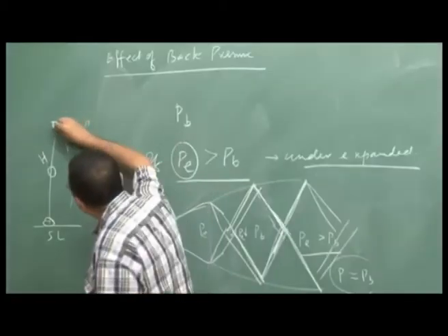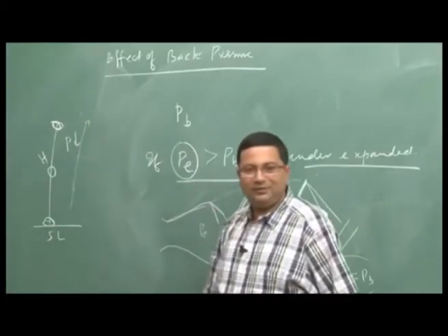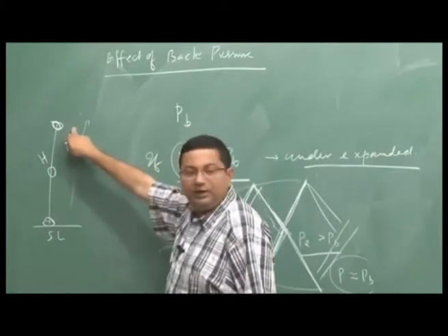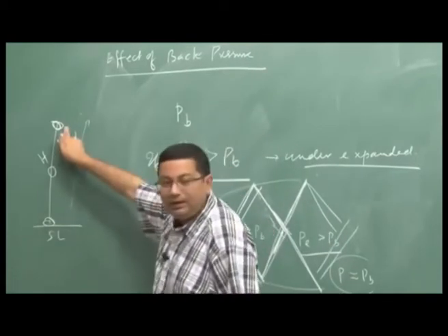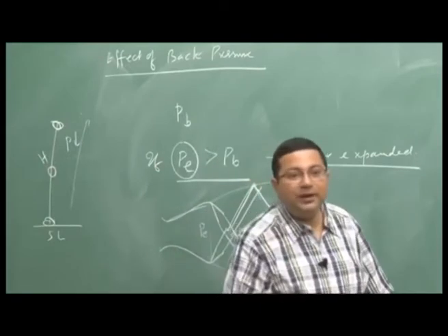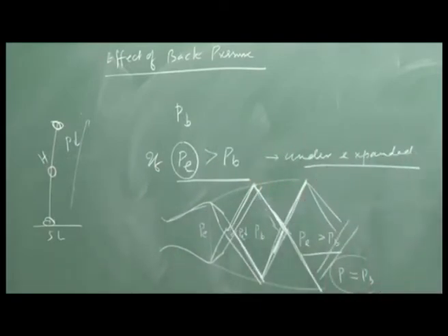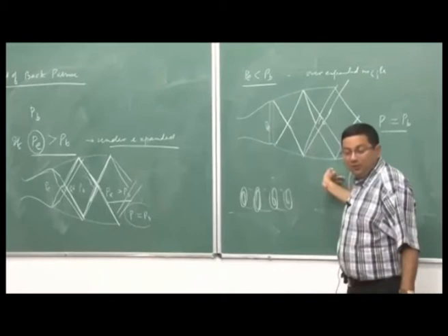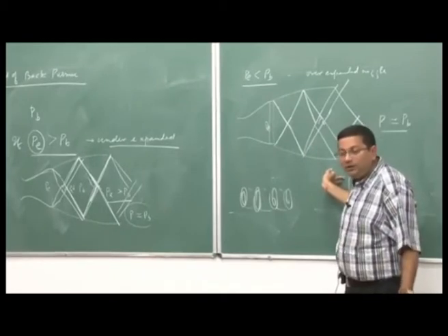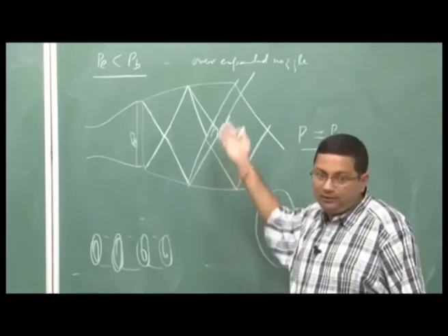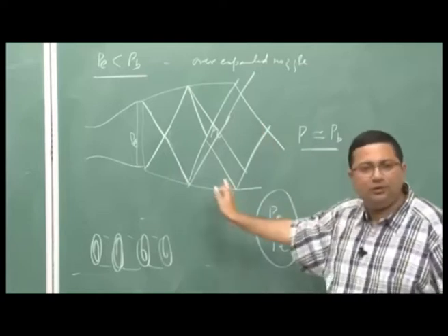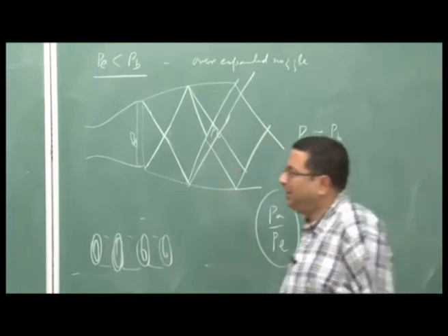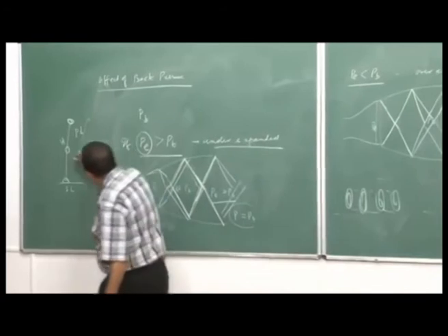If we design for this, where exit pressure is equal to the pressure here, then from here to here we have an over expanded nozzle, we get into these problems. So, once again that is something we do not want, again we never get optimum and in the flow, we can have separations and a lot of bad things happening. So, if we design it for somewhere here,